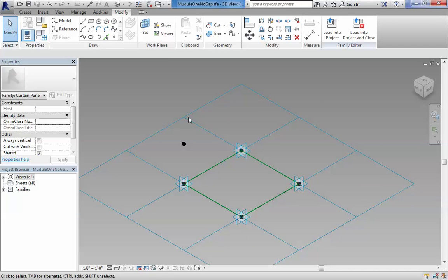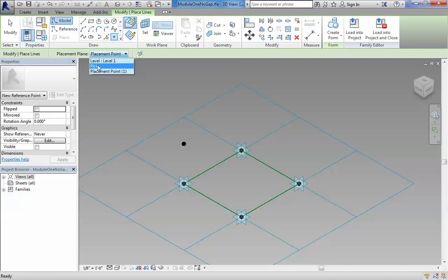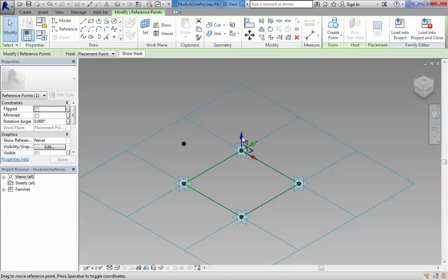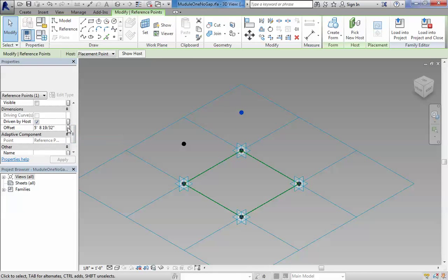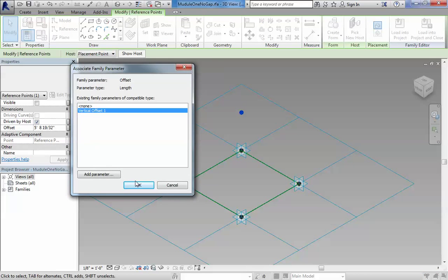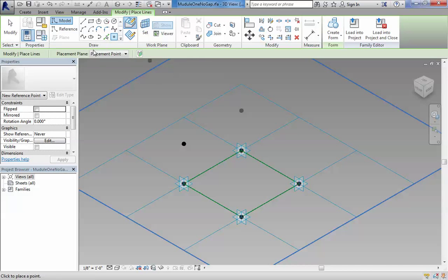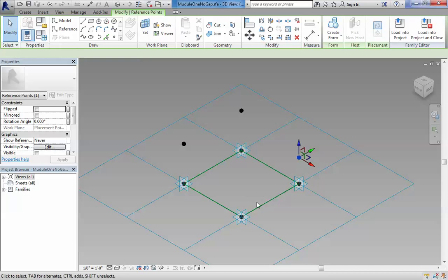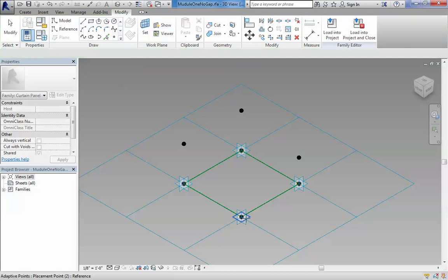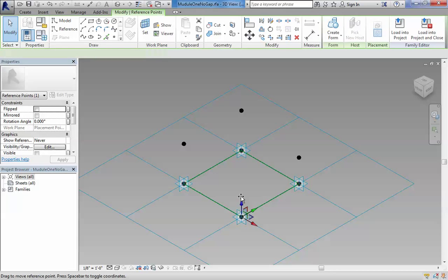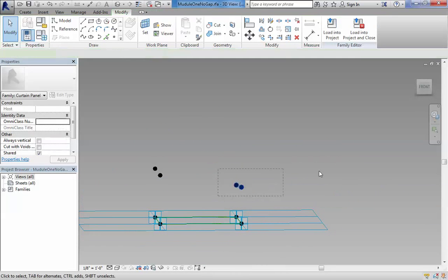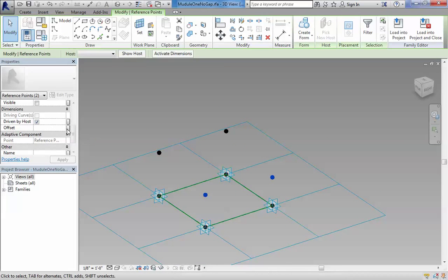We do the same thing 4 times, meaning point, pick, horizontal plane, place the point, escape, select the point only, and vertical. You can already go there and select the button to assign the same parameter, and it will automatically adjust. Okay, point, again, pick, select, place, escape, move vertically. I'm going to do the other one very fast. Pick, select the plane, escape, select, move vertically. Now I'm going to select these 2. I could have selected the 4 of them with no problem, and under the offset parameter assign this parameter so all of them are equal.